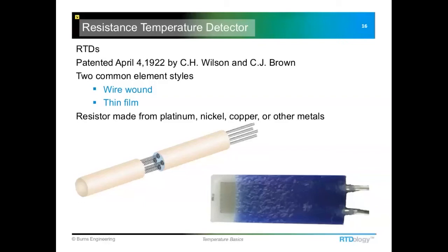But in some of the HVAC systems, we'll use a 1,000 ohm sensor. So if you were to measure that sensor at 0 degrees C, it's going to have 1,000 ohms of resistance. To be completely accurate, if you're dealing with a PT100, that's a platinum resistance detector as opposed to just a resistance temperature detector. You're probably better off just playing along and saying PT100. Yep, exactly. It's a little more specific.